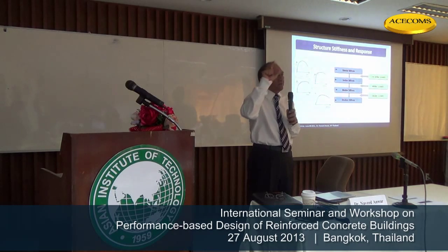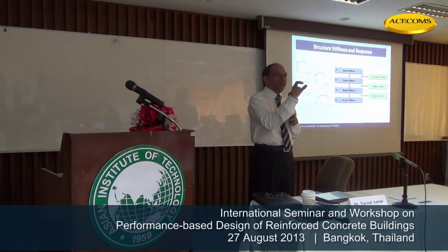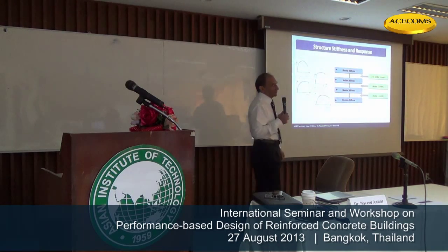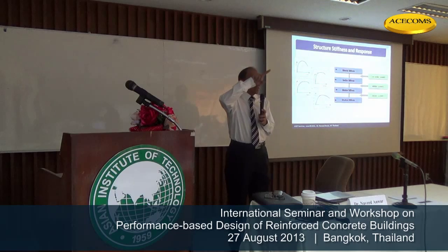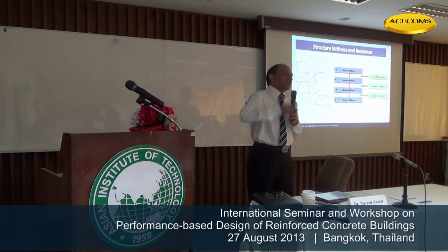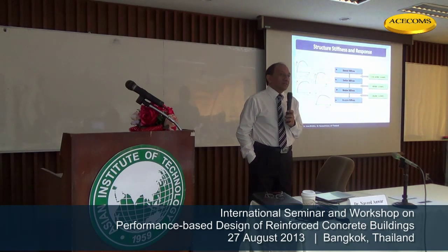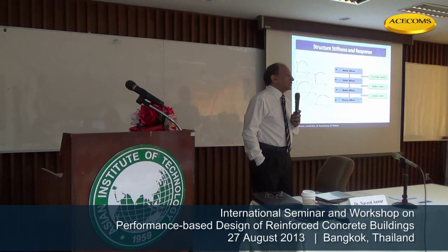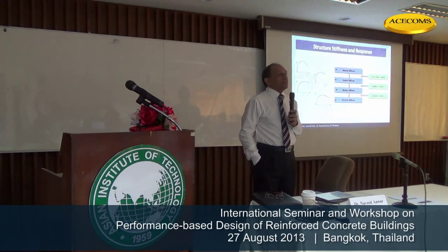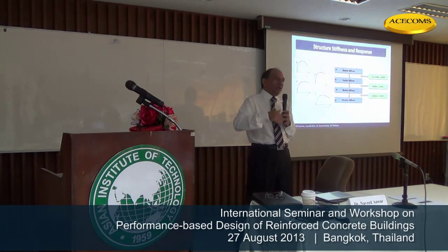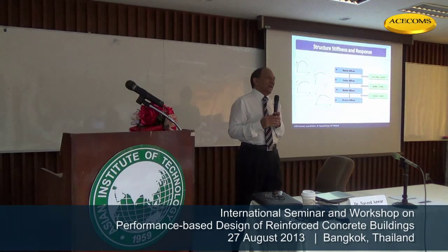Material stiffness multiplied by geometric stiffness, you multiply, you get the cross-section stiffness. Then comes member stiffness. Members can deform. And what is the stiffness of a member? It is the deformation divided by the length. And the length is also changing, so the member stiffness is also changing. Member shape is changing. I mean, the length is changing. Shape also is changing. P delta effects are coming in. So you have another level of nonlinearity added.